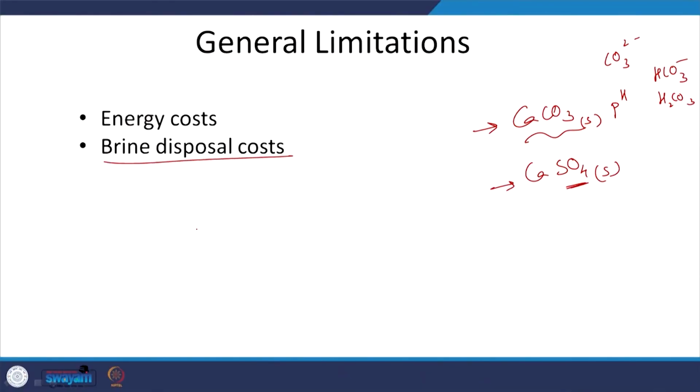So, the costs are pretty high with respect to operating the RO and also with respect to changing the RO membrane. And another aspect is you have the reject, or the concentrate. So, the brine disposal cost, what to do with this? Again, you can have a multi-effect evaporator or landfill or such. So, brine disposal costs are again considerably high.